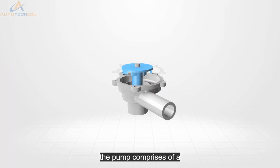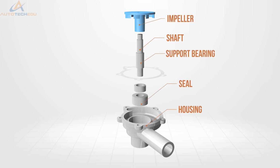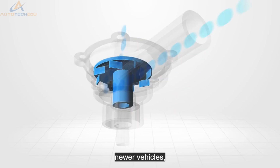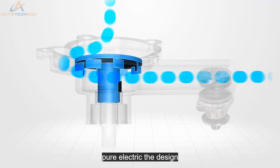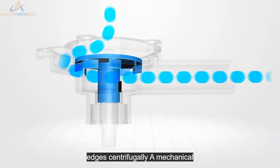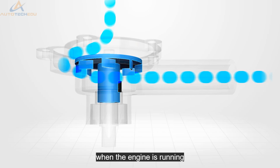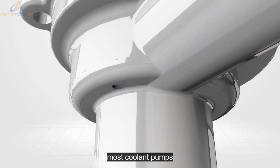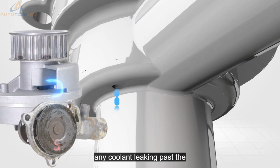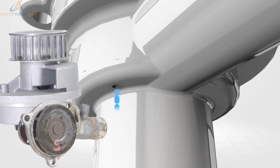The pump comprises of a housing, shaft, support bearings, seal and an impeller. They may be belt, chain or camshaft driven, or in newer vehicles, pure electric. The design of the impeller draws coolant to its centre and is forced to the outer edges centrifugally. A mechanical water pump will only operate when the engine is running. Most coolant pumps are cast with an atmospheric or weep hole that allows any coolant leaking past the seal to drain off before damaging the support bearings.